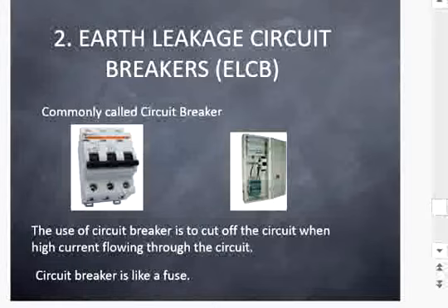Number 2 is another safety feature, what we call the earth leakage circuit breaker, or known as the ELCB. You can find this one arah circuit board, arah houses, arah sekolah pun ada juga. Okay, some if your parents use this term, or kalau ada ribut, okay, ataupun tanda trip, meaning the switch terturun. Apa maksud terturun itu? This is the one, ELCB ni, ia punya switchnya terturun itu maksudnya ia trip, terturun ke bawah. So all you need to do is just push it up, naikkan ke atas.